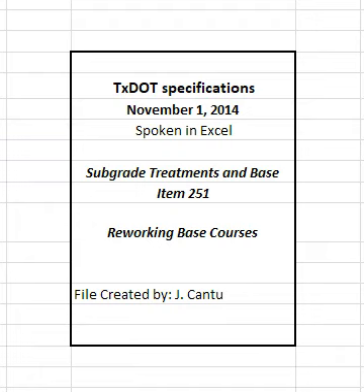4.2.5 Refinishing. Blade existing base surface to remove irregularities. Cure before placing the pavement on the refinished base, as shown on the plans or as directed. 4.3 Compaction. Compact using ordinary compaction or density control as shown on the plans. Bring each layer to the moisture content directed. When necessary, sprinkle the material in accordance with Item 204, sprinkling.